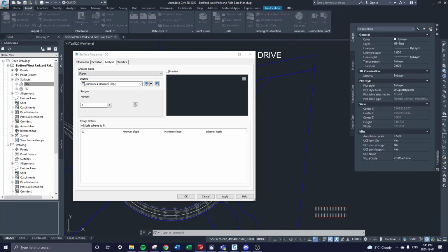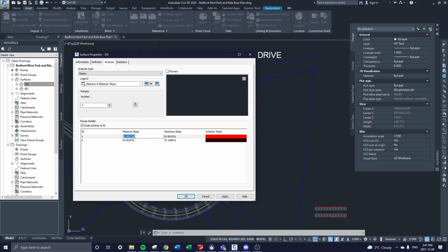So some of you might have already done this and have realized that, well, hang on a sec, that really limits where we can build. I asked Paul if you can still build within these 20% slopes. It just, you want to avoid it as best as you can. And this is just to limit how much excavating you're going to be doing.